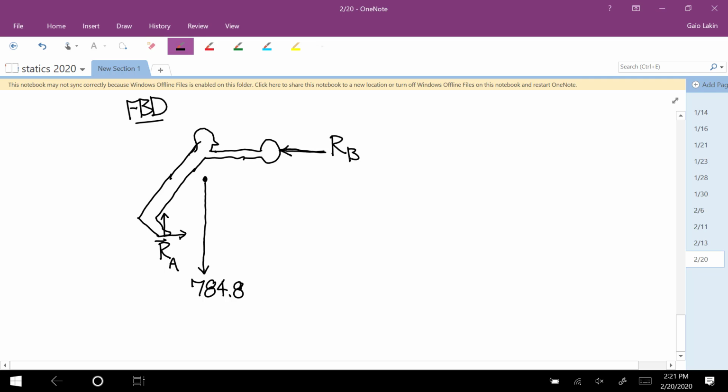And notice that with the dimensions that I gave, we know the horizontal distance between these two, but I didn't give a height of the center of mass. And we know the vertical distance between the floor and the RB, but I didn't give a horizontal distance for when that force is applied. So really, if we're using the definition of the r vector, we can't calculate those r vectors. We don't have a vertical component for this one, and we don't have a horizontal component for this.